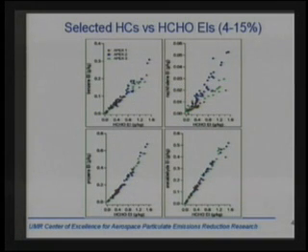As we get down to some of the more trace species, benzene shown up here, again, the correlation is quite tight. That's the upper left panel. When we get down to naphthalene, it's starting to get to be one of the more trace species that we're measuring. There is now some significant variation among the different campaigns. Interestingly, for each campaign, they're actually very tight. So even with a wide variety of different engines in Apex 3, that's the green color there, or the wide variety of CFM56s we looked at in JET's Apex 2, the correlations are actually quite tight. We suspect that maybe there's a fuel variation, maybe an ambient temperature, but here we're talking about things that are a fraction of a % of the overall hydrocarbons.